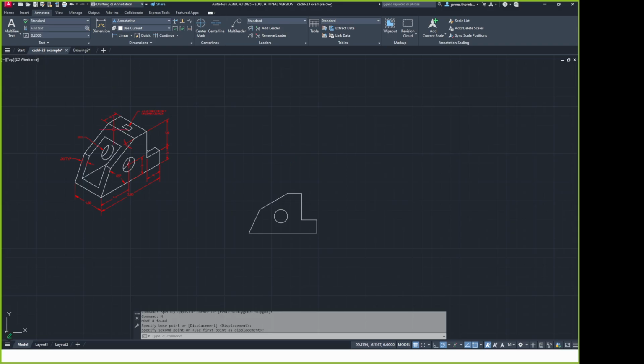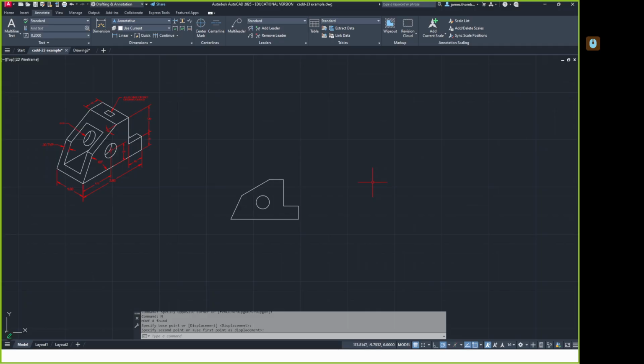I'm looking down at the top of this thing. The sides, right? Yeah. So maybe on the side view, if I look at the side view, will I see the entire shape of it? Yeah. So you could do the top view and then just offset in your sides and then use that to project to the side. That works. Or you can do the side view where you can see more of the outer shape and then project to the top. Who votes for top? I want hands. No? Who votes for side? Okay, side wins.